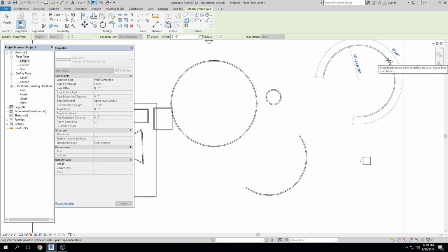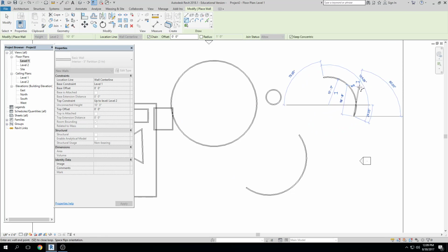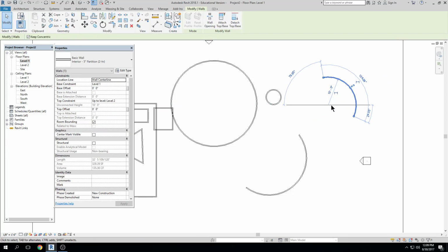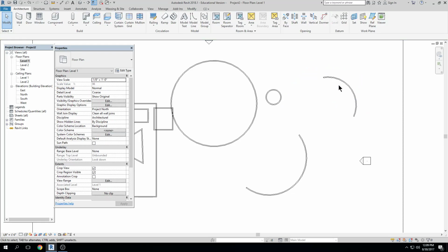So I can choose to have it whatever direction I want. It's very easy, right? I can preview what's happening. I could type 15, enter, and I have an arc with a radius of 15, right? So pretty easy to use. And I actually don't use arc in Revit either, because usually when I'm trying to create a rounded corner on something, which is what an arc does, I use fillet instead, or trim, right? So there, I just move my way around arc.